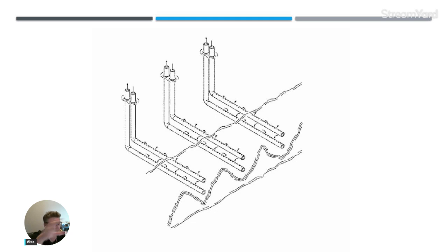So now that steam could be migrating from one well to another. So, what is the solution to mitigate the challenge? It is to co-inject NCG, non-condensable gas, something that doesn't condense like steam, able to maintain pressure, maintain oil production, and reduce the SOR.